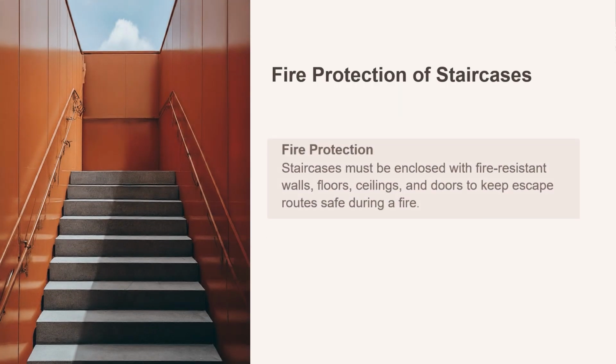Let us continue our discussion on staircases by focusing on the fire protection and strength. One major key point here is that staircases should be enclosed with fire-resistant walls, floors, ceilings and doors. Why? Because this helps to keep escape routes safe during a fire.